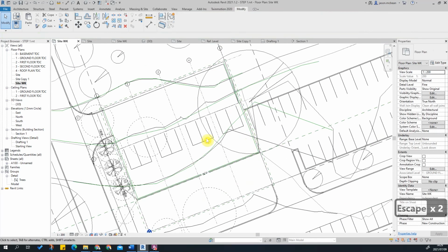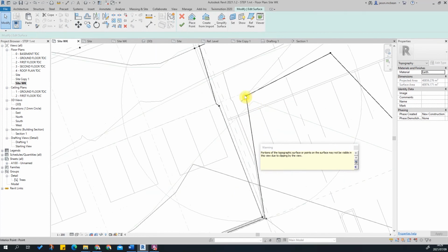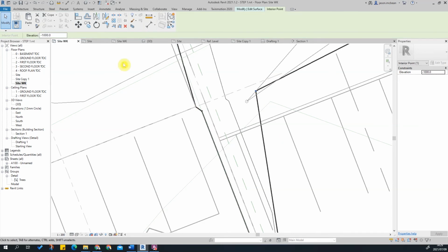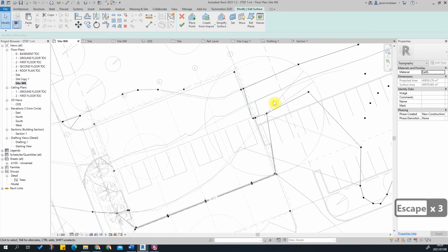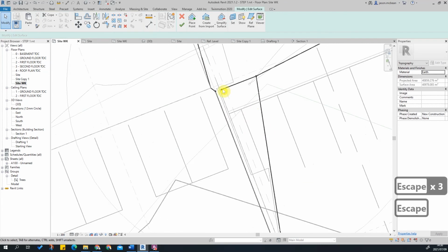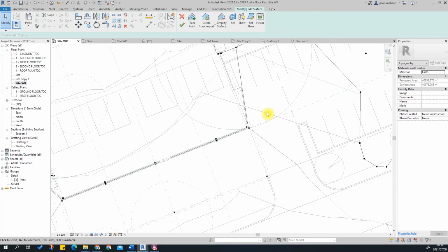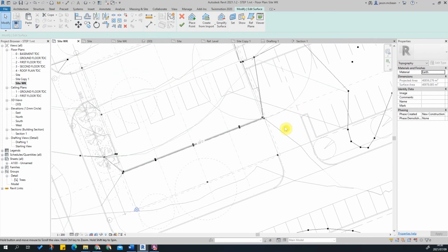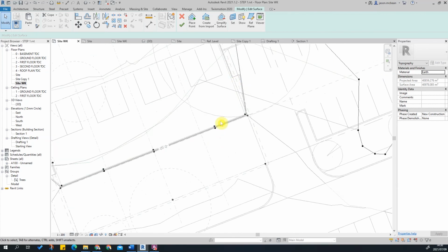Okay, so let's just go back to our topography. Edit topography. So here we've got a point that is 1,000. So here we just need to copy this point, copy once more, and put it over here. So now we've established a bit of a break. Okay, so here we might have to, you see our meter comes here. Here's our in-betweener, our -500. Where's our -500? Which is this line over here. So I might want to introduce that -500 here as well.